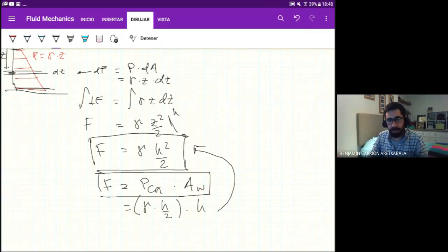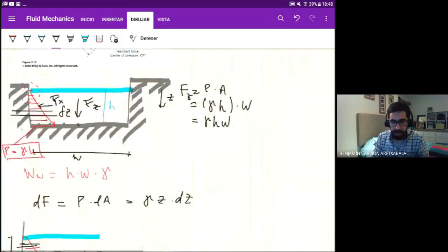But this is to show you that you can always compute the total force by integrating the forces at each depth, which is the same that we did before. If you know the pressure at the bottom is flat, we know that the pressure is the same everywhere. So basically you're integrating the pressure over a delta area, you get P times area, because you're integrating the area, okay?